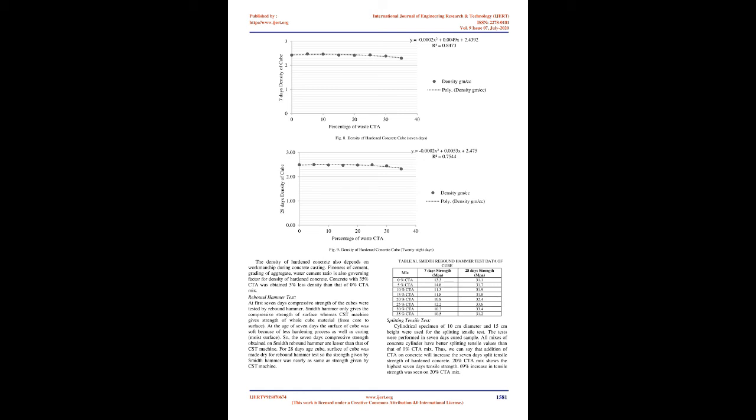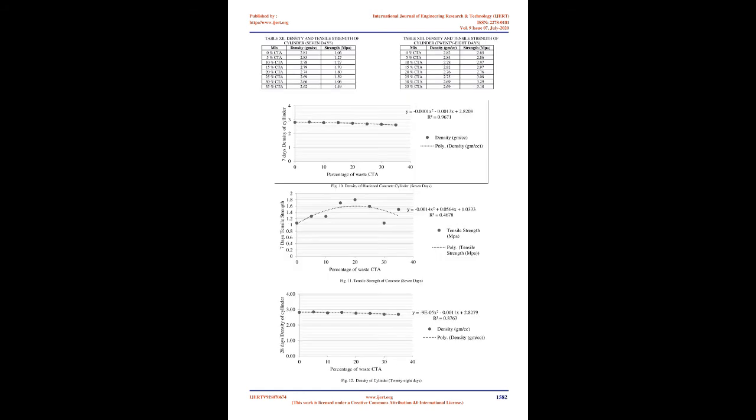383-1970. Fineness modulus. The fineness modulus, FM, is an empirical figure obtained by adding the total percentage of the sample of an aggregate retained on each of a specified series of sieves, and dividing the sum by 100. The fineness modulus of sand used is 2.91. Water absorption and specific gravity. To determine the water absorption and specific gravity of fines, i.e. sand, a pycnometer was used, and the procedure was in accordance with IS 2386 Part 3 Cl. 2.4.